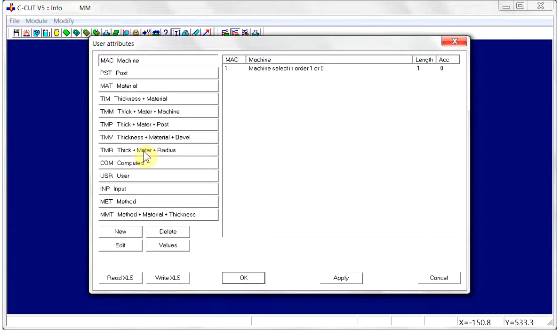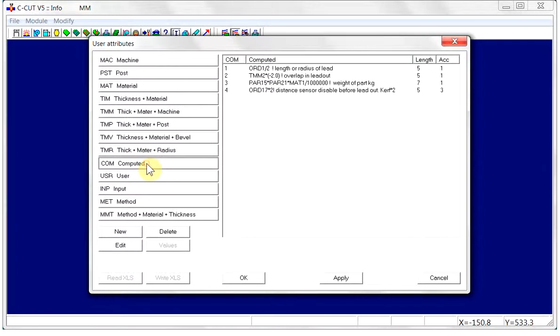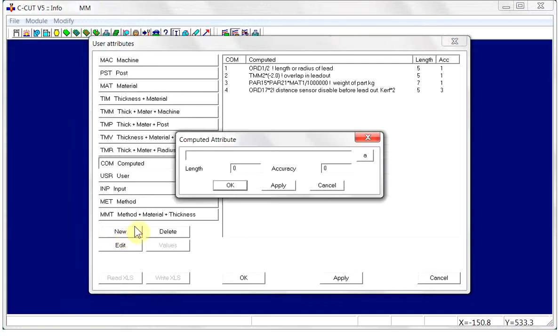We can use the value of attribute material plus thickness plus amperage for speed. For better accuracy, we go to Program Attributes and we pick the current speed in the cutting sequence, as the database speed could be modified.